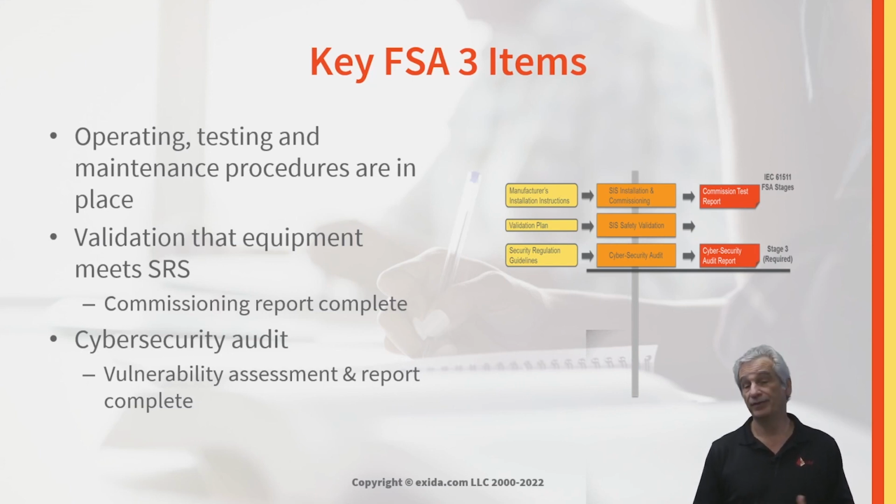We've made sure that the equipment has been properly installed according to manufacturer's recommendations, that we've configured everything correctly, and we've done our final cybersecurity audit to make sure, again, the barrier devices are installed correctly, the rule sets are there, everything's fine before we start up. Because during installation commissioning, of course, we could introduce some potential vulnerabilities. So this has to be performed before we start up.